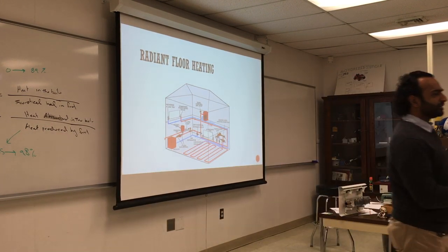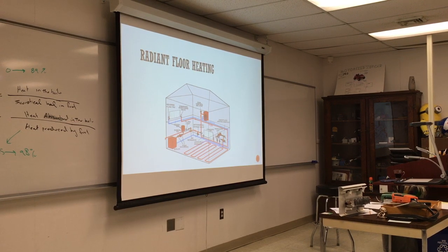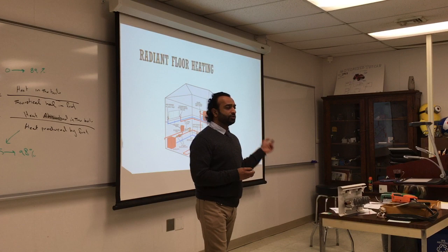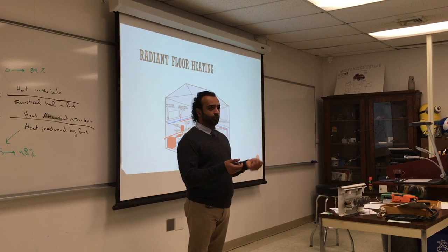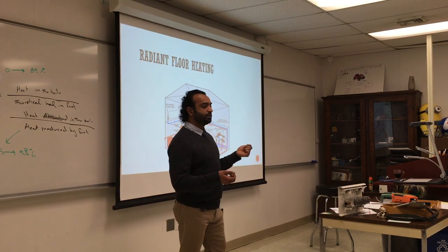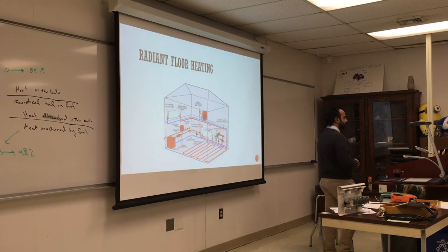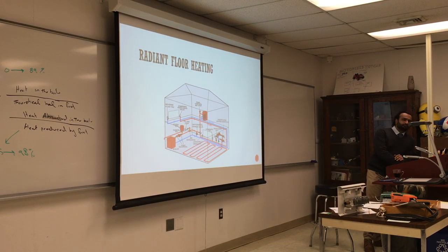Question? Can you run your boiler at a lower temp? Yeah, you can. Maybe up to like 120? You saw the aquastats, right? They have a high limit and low limit. You can put it between 120 and 140. It doesn't hurt the boiler running cooler. Really? Or could you set it as a priority zone, and then as soon as it hits that temp, it'll just switch over to the next zone? Yeah.